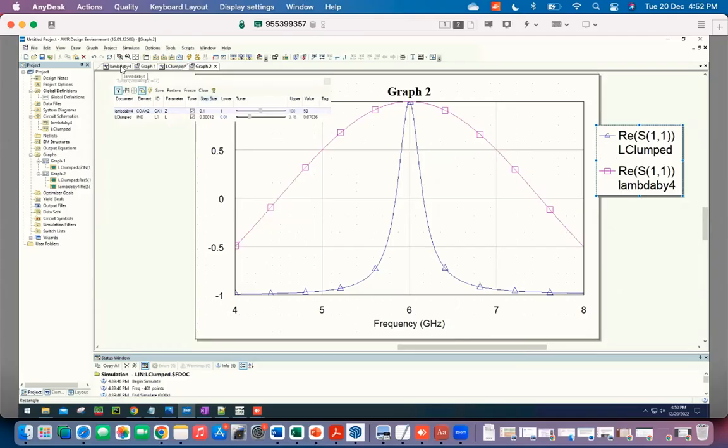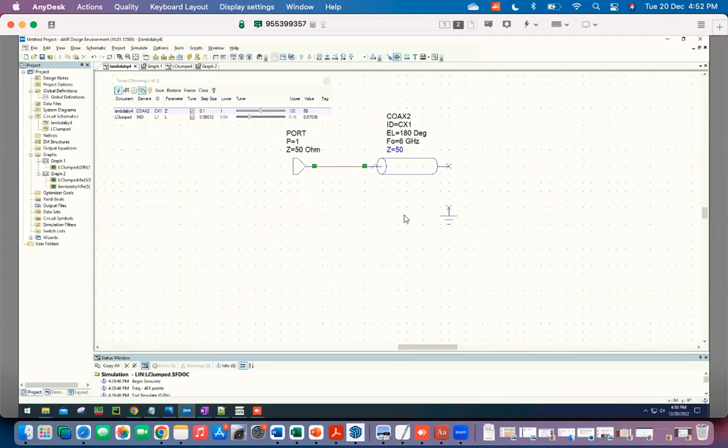What you need to do is to reduce the coupling of this resonator. So remember, the resonator is basically just this transmission line with these two boundary conditions. The problem is that the boundary condition on the right side, which is an open, is a very strong boundary condition. But on the left side, it's actually just a 50 ohm transmission line. And this is a 50 ohm load, and this is a 50 ohm transmission line. So in some sense, there is really not much of an impedance mismatch going on between these two. So it's not a very good mirror, if you look at the optics picture.